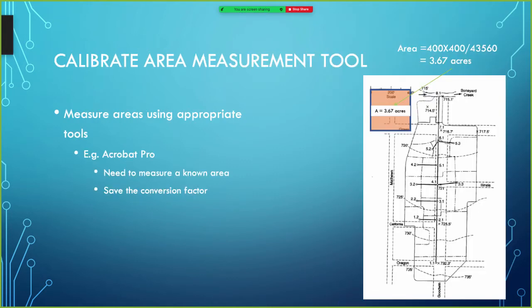And then we need to measure the actual areas involved with those various polygons. So use an appropriate tool. For instance, in Acrobat Pro, it has the ability to load in a JPEG or a PDF file, and then you can measure areas on the picture, and it usually reports them in things like square inches or millimeters squared. So we need to have a physical scale somewhere.